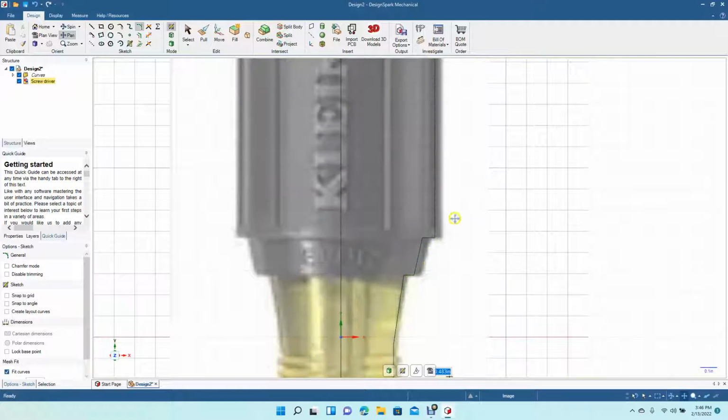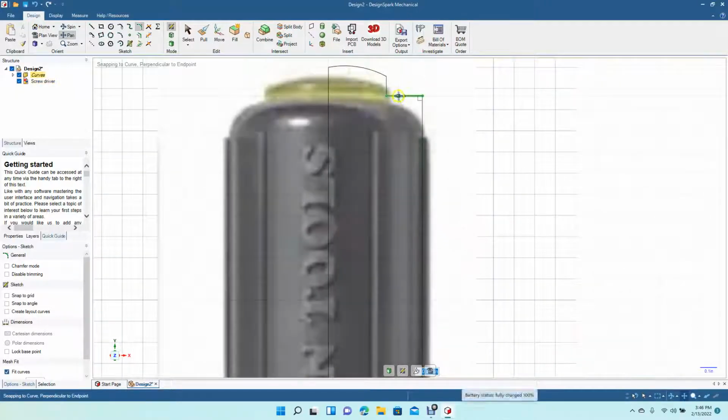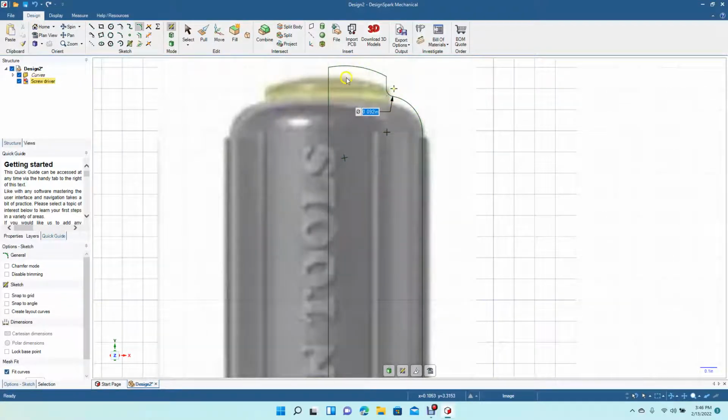I think these are okay straight. We'll pan up to here. Let's go ahead and get the create rounded corner. We'll click there, and then we're going to pull down to 0.215. And then we're going to put a little fillet in here. So we'll click 0.046. Click.